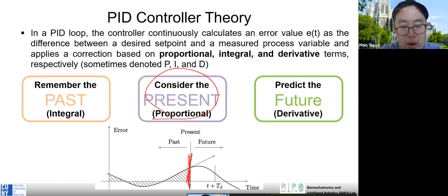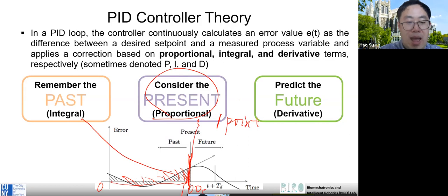However, you already know this history, right? For example, from this to this, let's say this is 100 seconds. You already have the data from the last 100 seconds. So if you only use P, you only use 1 point. If you use the history data, you can use all the 100 seconds of data. So that's the history term.